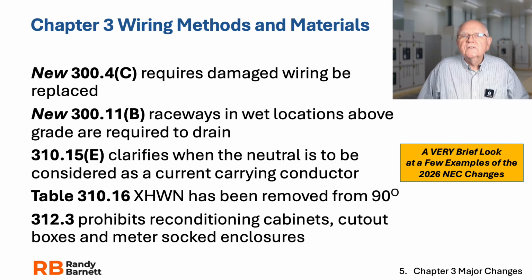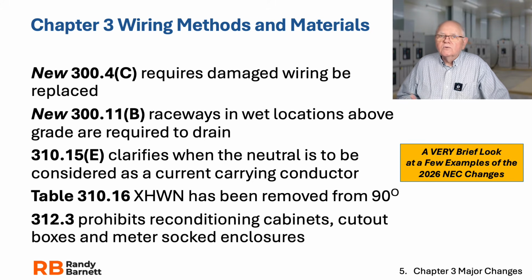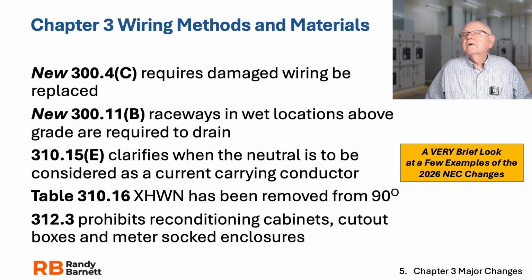Another new one, 300.11B: raceways in wet locations above grade are required to drain. We've always known conductors inside a raceway, inside a conduit in a wet location, inside the conduit is still considered a wet location. Now 300.11B says that raceway is required to be able to drain, right?